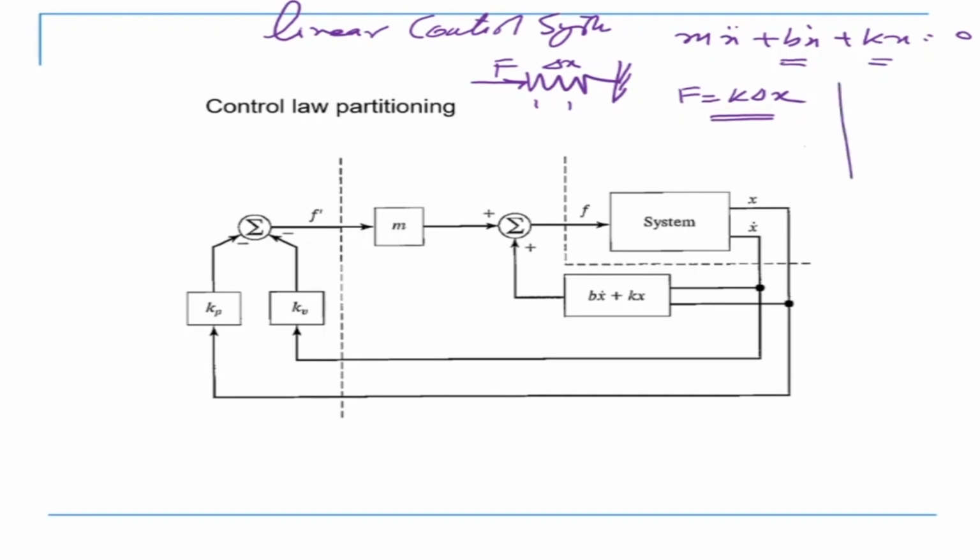So if I draw the graph of deflection versus force, this is my force, and this is deflection, say del x. Initially it could be a straight line like this, and that is linear, then it goes off like this. This means that it is linear only up to here, and after that it becomes like this. Why? Because further deflection will not be possible. You can imagine that suppose I keep giving a force, it will compress. Once the coils get compressed, then you have to give a large amount of force to get deflection.